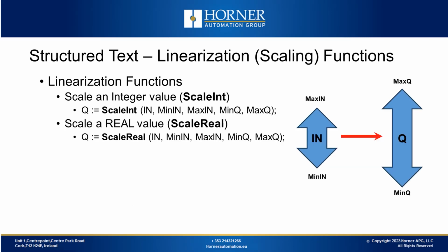Now we'll look at some practical uses of mathematical operations that might be more apparent. We commonly employ addition, subtraction, multiplication, and division for tasks like linearization, especially in industrial settings where scaling of analog values is frequently required. You can implement linearization using the straightforward equation y equals mx plus b, and we'll provide an example shortly. Additionally, there are specialized scaling functions available, including integer and real value scale functions, which we'll demonstrate later.